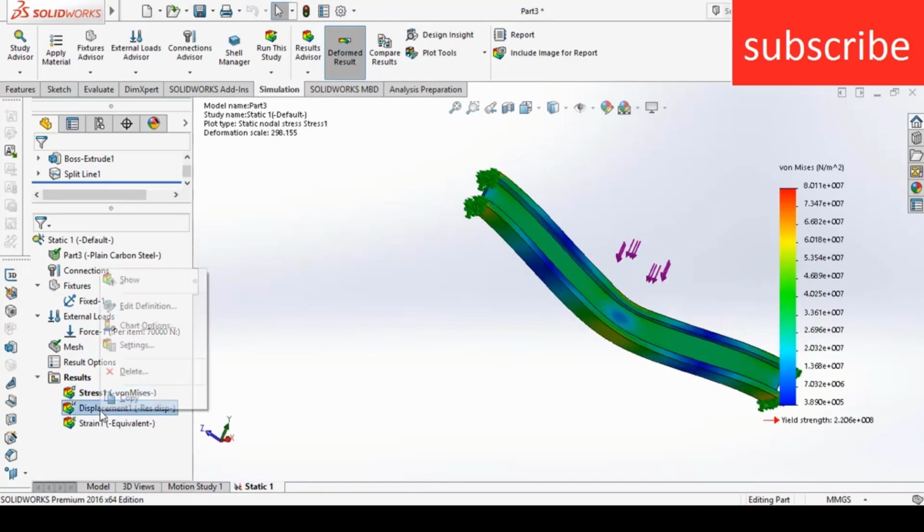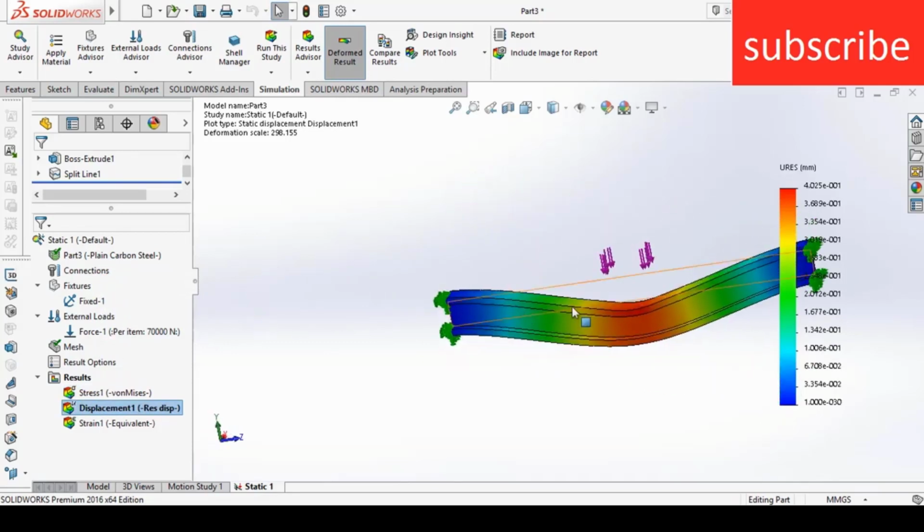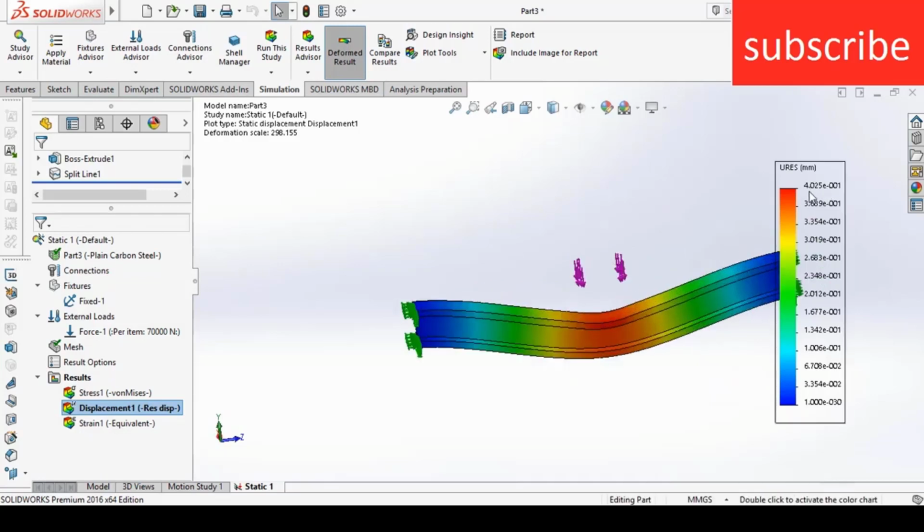Now go to displacement, right click on it, click on show. Now the first thing you see is that the beam is bending too much, but here you will see that the deflection is currently 4.025 × 10^-1, which is not the real value because the beam appears way more deflected. So why is it showing me like this?